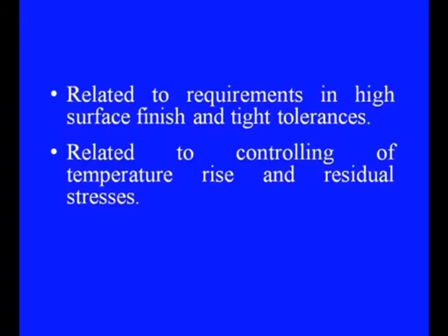Another point is related to the requirements of high surface finish and high tolerances. Then, related to the controlling of temperature rise and residual stresses. These are also considered very important issues, as if high temperature is developed while machining, it can cause some damage to the part. If the part dimension is relatively very small, there is a possibility that due to this high temperature developed during machining, the entire part may get affected, which is at times undesirable. Therefore, we had to look for some processes in which these can be at least minimized, if not eliminated.